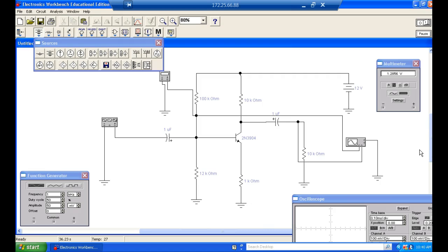We've got a power amp over there. I need to go find where it's burned up, but you can actually see the two channels come down through there and how they work through that thing. Power amps still use a lot of discrete components. Your radios have been around for so long that your preamps and your power amps are in one integrated circuit. So now if you got a radio in your car that goes out, odds are you're going to replace the radio, because they're just about unrepairable. Power amps, though, if you got the schematics on the power amps, those are still very repairable because they still use a lot of what we call discrete components.